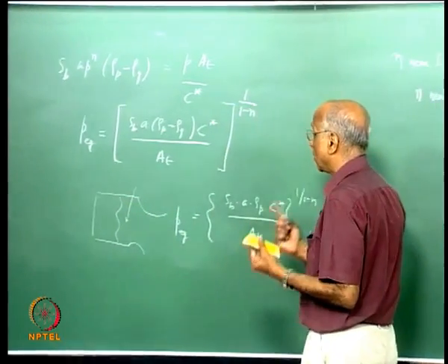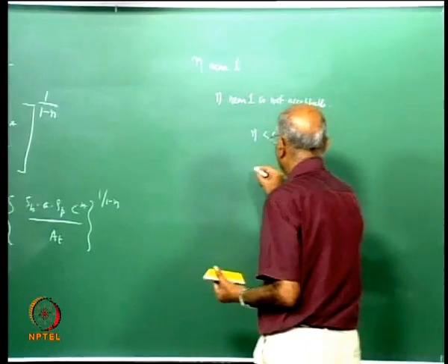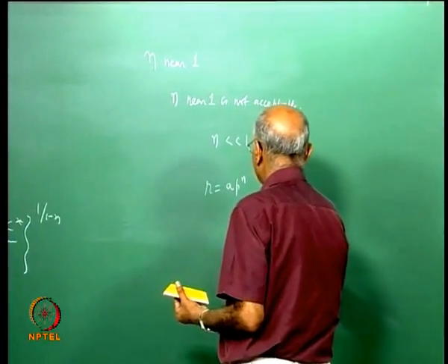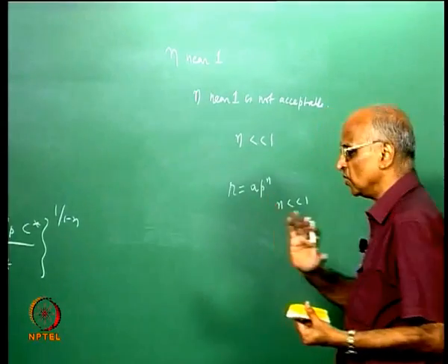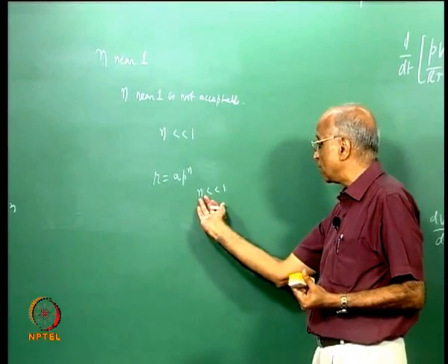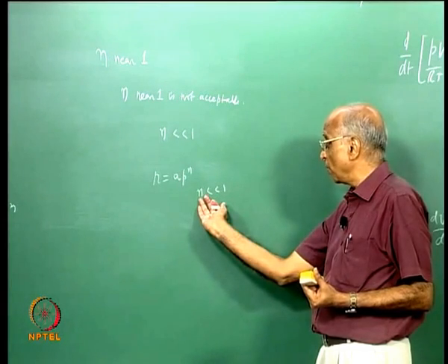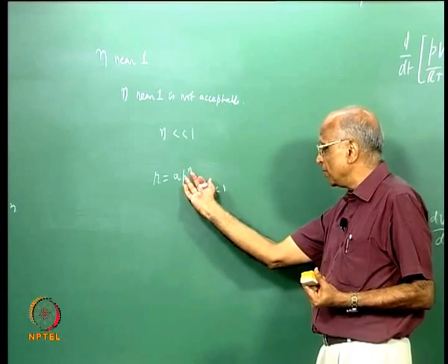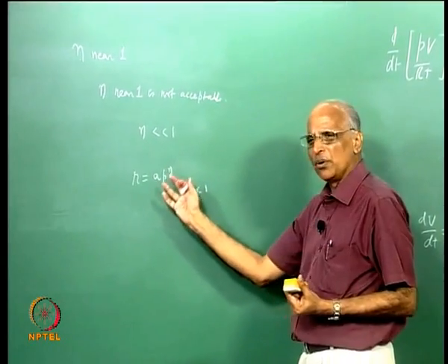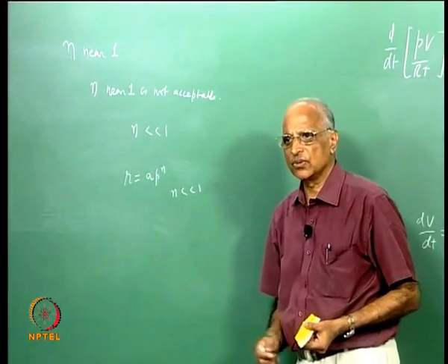Therefore, we tell ourselves that one of the qualities required in the burning rate of a propellant, r equals a P to the power n, is that n must be a small number; a large number is just not acceptable. For composites it is around 0.3, 0.25 to 0.4, while for double base it is near 0.5, 0.4 to 0.5. Therefore maybe composites are a little better than double base propellants.